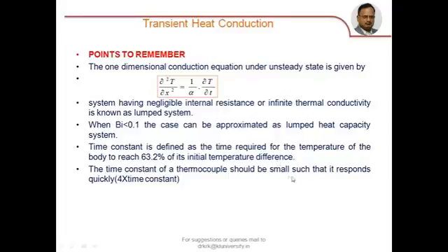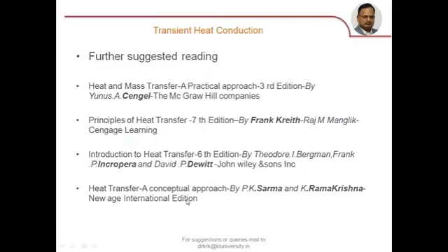The time constant of a thermocouple should be as small as possible so that it responds quickly. In general, you have to wait for not less than 4 time constants to take the initial reading.